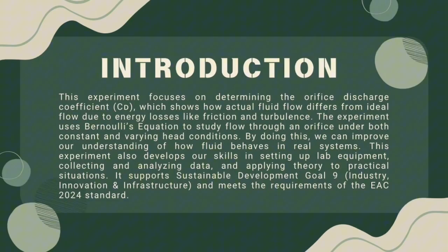For the introduction, this experiment focuses on determining the orifice discharge coefficient, which shows how actual fluid flow differs from ideal flow due to energy losses like friction and turbulence. The experiment used Bernoulli's equation to study flow through an orifice under both constant and varying head conditions. By doing this, we can improve our understanding of how fluid behaves in real systems.